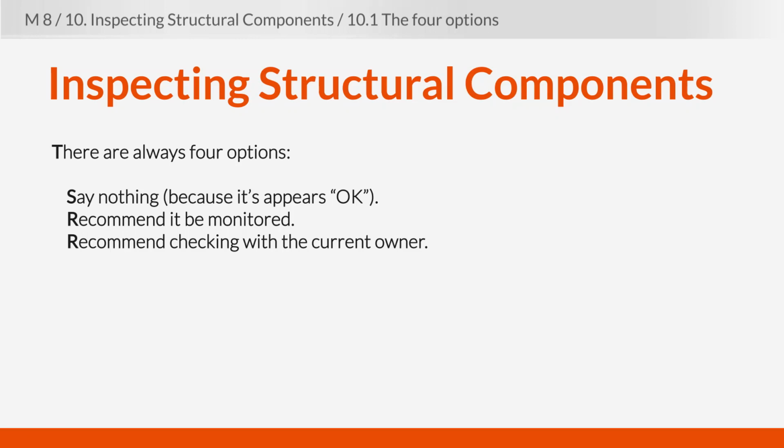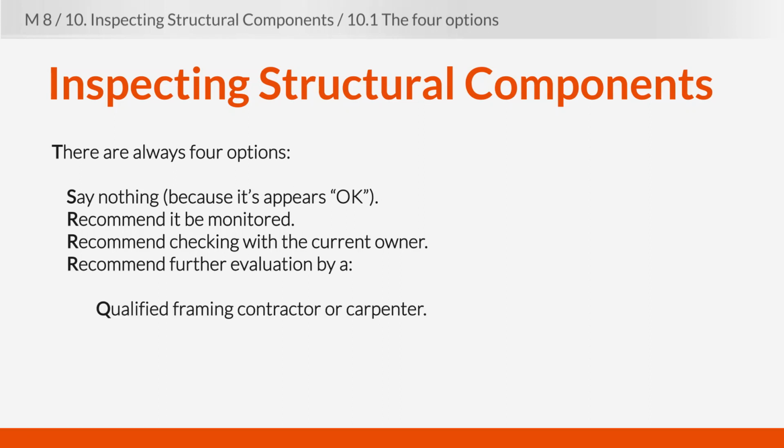The fourth option is to recommend further evaluation. Now you have 3 subcategories of that. You can recommend further evaluation by a qualified framing contractor or carpenter, same thing, or further evaluation by a qualified foundation contractor, or you could recommend further evaluation by a licensed structural engineer.